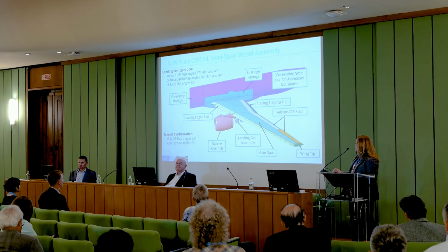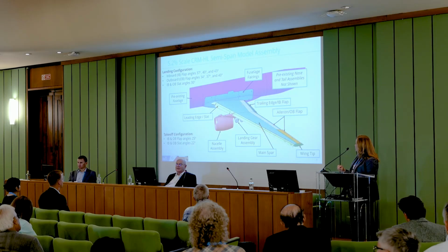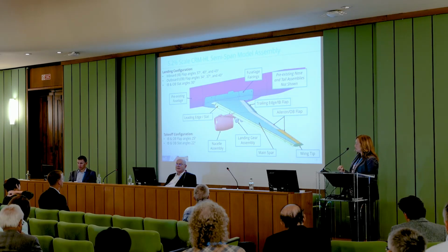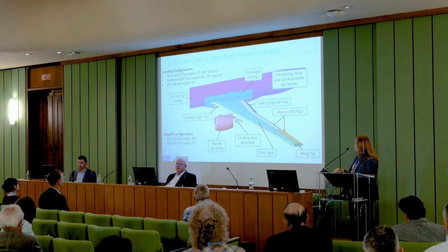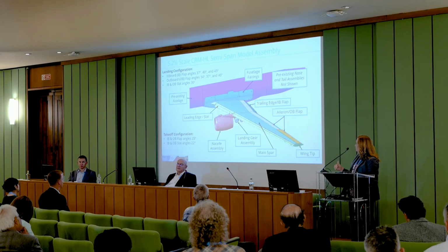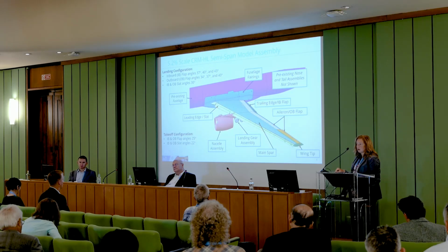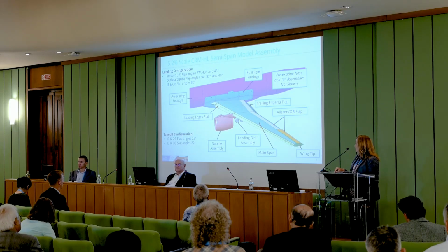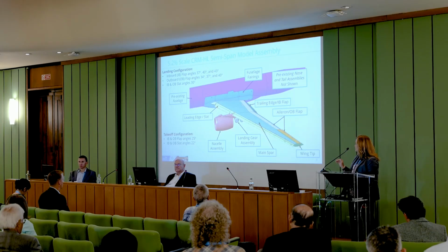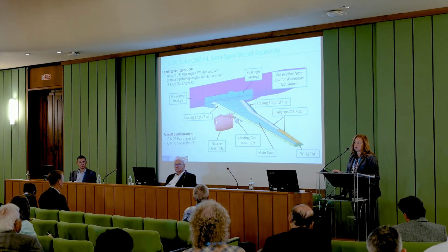For the landing configuration, we built 3 different inboard flap angles: the nominal, which is 40 degrees, and then +3 and -3 degrees. The outboard flap angle, the nominal 37, and then plus and minus 3 degrees on either side of that also. The slat angle was 30 degrees inboard and outboard as defined in the reference configuration. And then for the takeoff configuration, we left the inboard and outboard flap angles at 25 and the slat angles at 22. All of these were defined for the reference configuration.